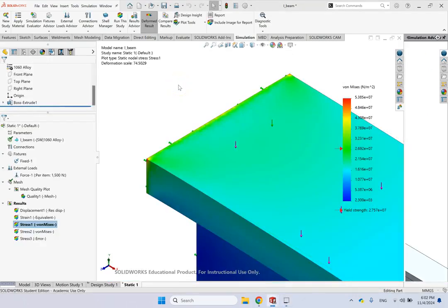So hopefully I could answer those questions and make it clear where to look for those singularities, why, based on the theory, based on these energy norm errors and so on, and the difference between nodal and elemental values, and to make the results better, maybe adaptively, and get results that you can trust more and do a better design for.